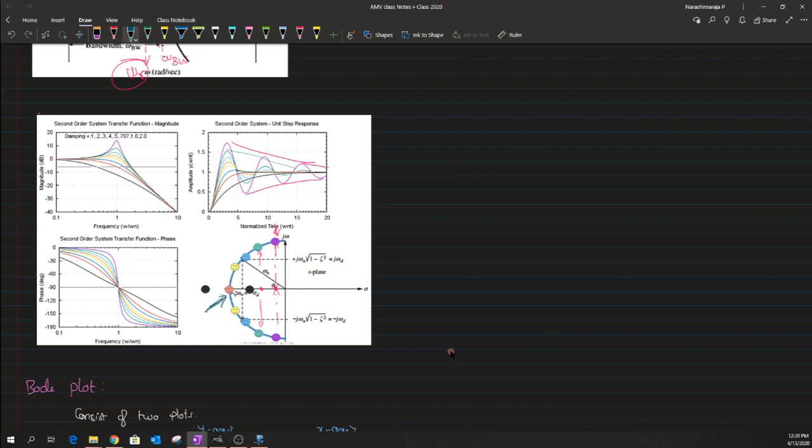Yeah, so when we use this orange color, you can see we are under the critically damped condition. Under this critically damped condition, the response will not have any sort of peaking. So no peaking will happen when we are at critically damped condition, and the output would respond a bit slower than the underdamped condition. It will not reach the output fast.